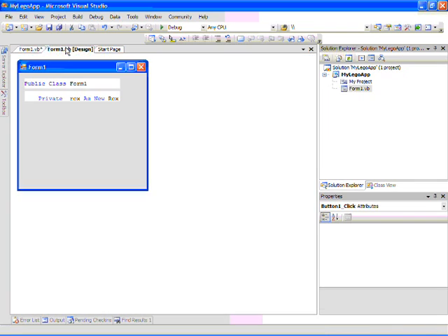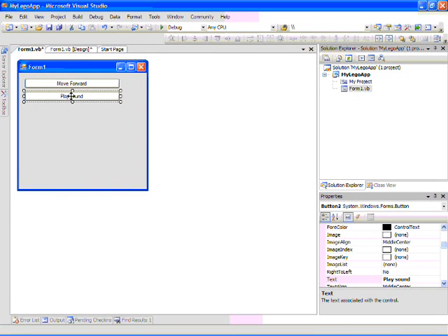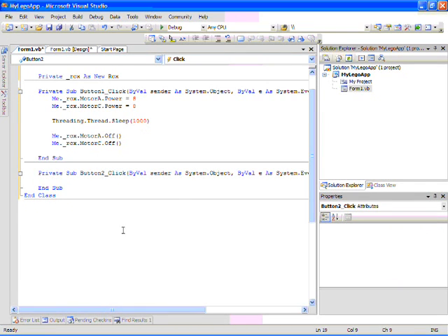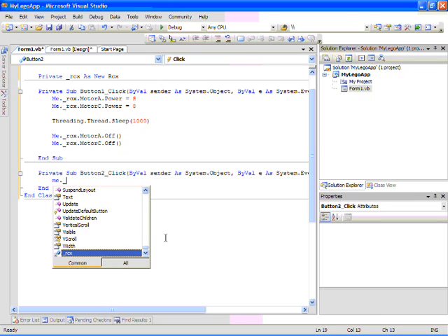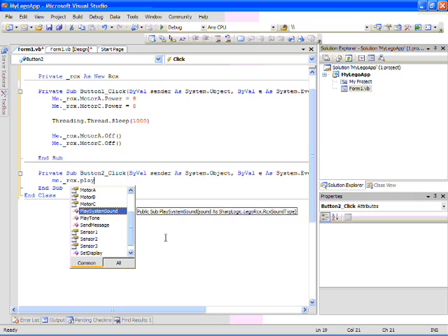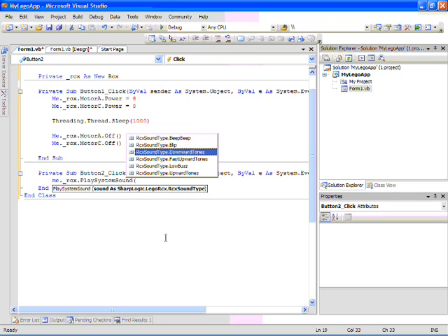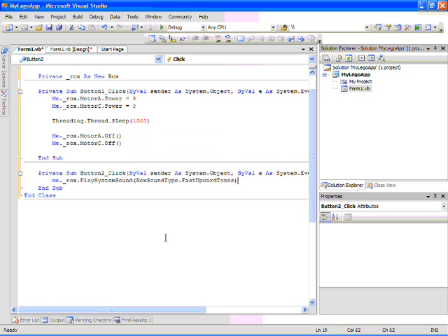We're going to go back to that application again, and we're going to configure the UI so that we can play a system sound when somebody presses the second button. So on the RCX, we're going to say play system sound, and we're going to have it play the fast upward tones. Each of these enumerations maps to a specific LASM configuration command that is built into the firmware on the RCX. So those 6 different system sounds are actually available natively in LASM on the device.